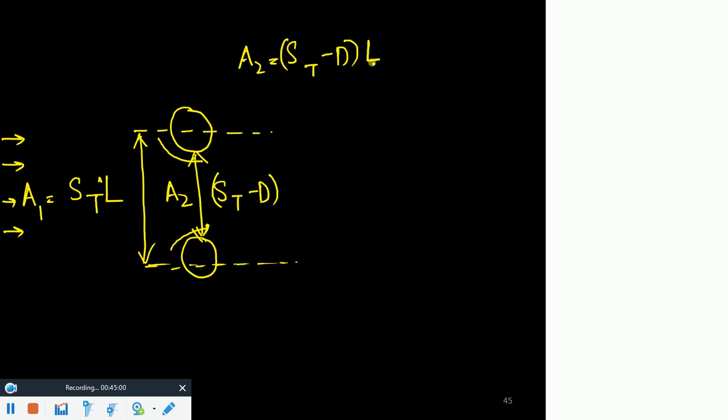Now, a very important point: in these applications, Reynolds number is defined with the maximum velocity, not with the oncoming velocity. If I define this Reynolds number, I would say V max, not V infinity or V incoming, multiplied by diameter over nu. So the problem is we need to find out where that maximum velocity occurs.